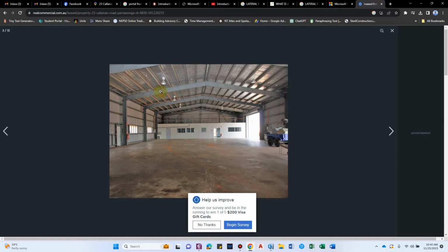So this is a portal frame, and whatever the wind load comes from this direction, suppose this cladding, the load acting on this cladding gets transferred to this frame, and with the portal frame action the load gets to the foundation. However, for the other direction, if the wind blows from this direction, these claddings are subjected to the wind action, and that transfers load to these columns.